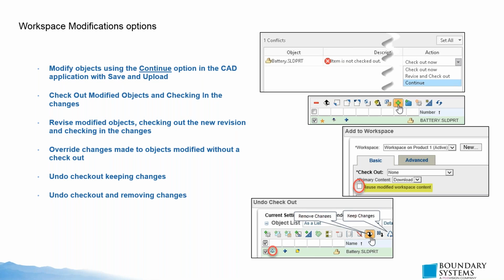And if it happens that the modification or the brainstorming session gets approved, you don't lose that data. So even the modified data can potentially be checked out and checked in if it's not released. But if it's released, you could initiate a revision, check out the new rev, or potentially add the new revision with all the modifications, because the new rev is not going to delete any of the changes you made, and you could add that to your ECN process and get it checked and approved.